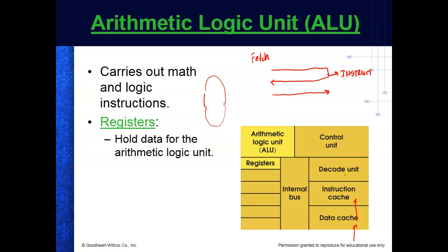The book calls stuff outside the microprocessor registers, but that's not true. They're going to be data files, and we'll make sure we get that corrected. If you ever get inside the actual documents for the processor provided by Allen Bradley, they don't use the term register. They'll call them data files and data bits. So we'll try to correct that in the book, because registers are inside the processor.